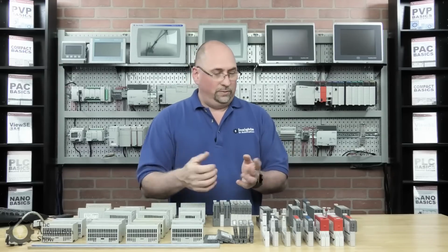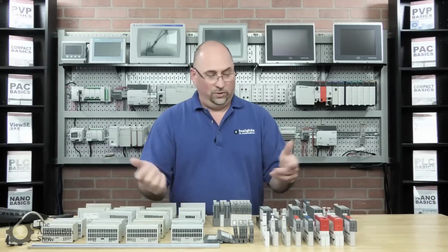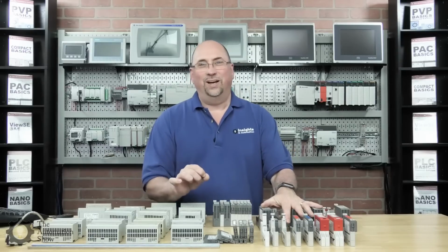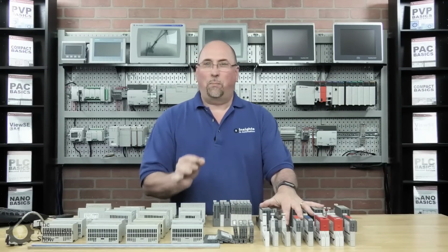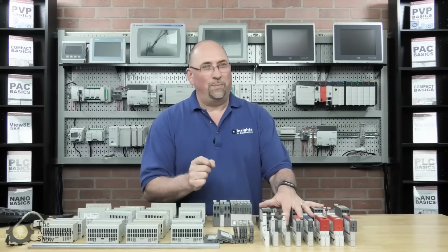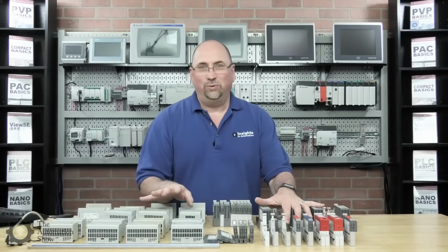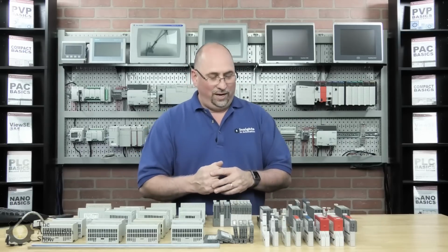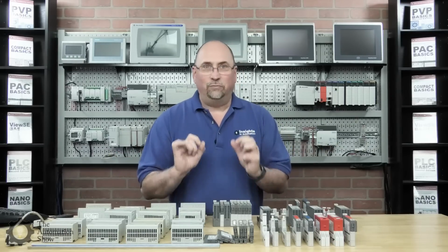As a matter of fact, it was actually easier to use DeviceNet. I know a lot of people are cussing at me right now, but it was actually easier to use DeviceNet with analog on the SLC than it was to use remote I/O analog. But in any case, I do believe there initially was a remote I/O adapter for Point-IO when it first came out, and I think it was pulled off the market pretty quickly. I didn't have a chance to research that, but that's what this old man's memory is telling me. But in any case, those are the common things between the two lines. So they have a lot in common, but they also have a lot of differences, right?